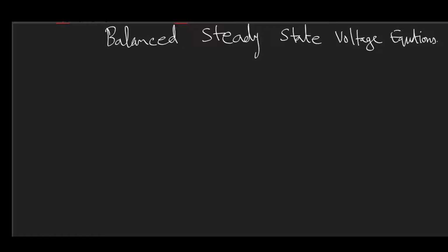Now, if the three-phase system is symmetrical, then it is balanced. Don't get confused between balanced and healthy system. Even a faulty system could be balanced. The condition of being balanced is just that all the phases are carrying identical value of current or experiencing identical amount of voltage drop. It has nothing to do with whether the drop is within the permissible limit or beneath that, whether it is due to the fault or due to some unbalance, some undesirable factor.